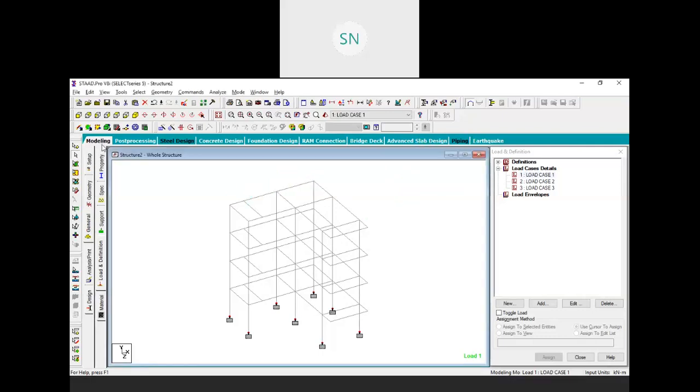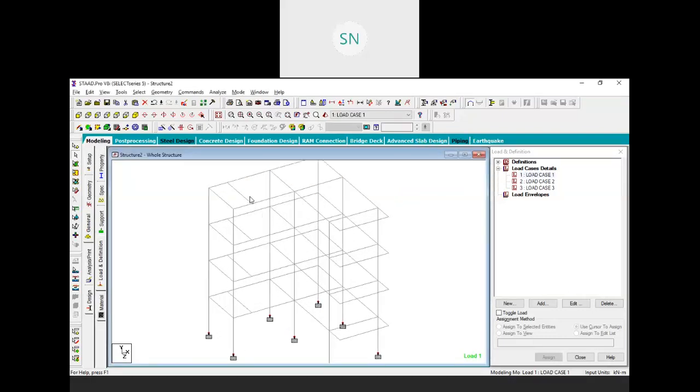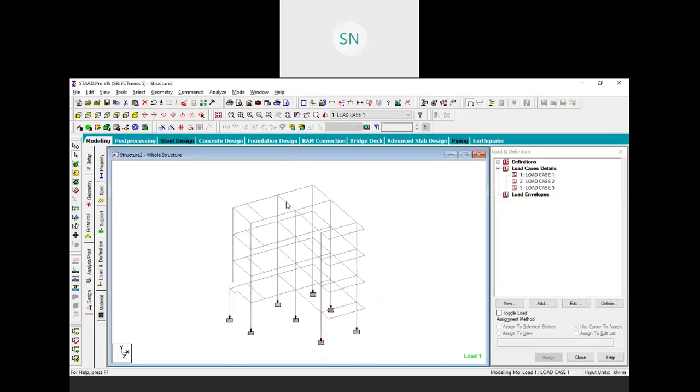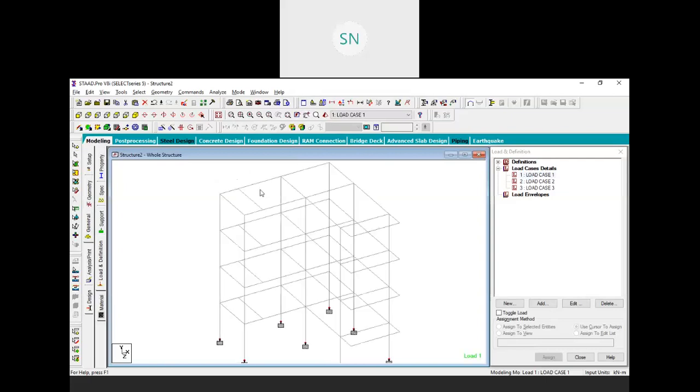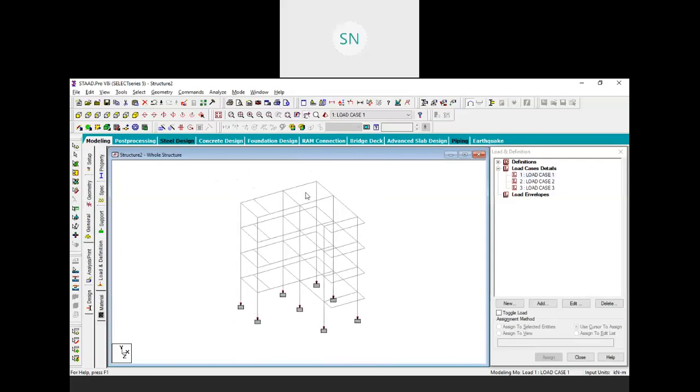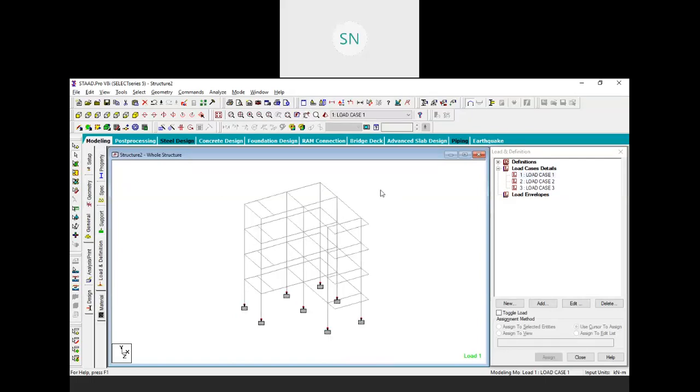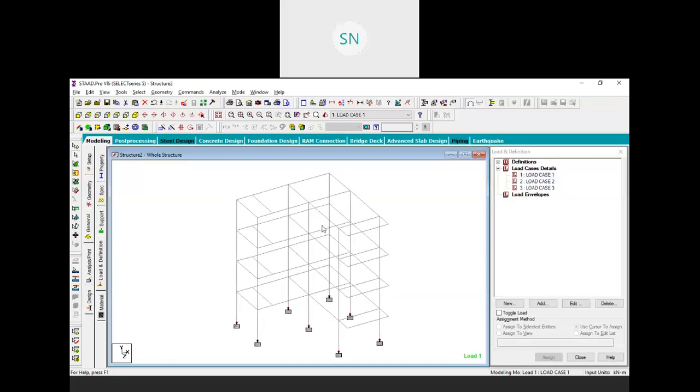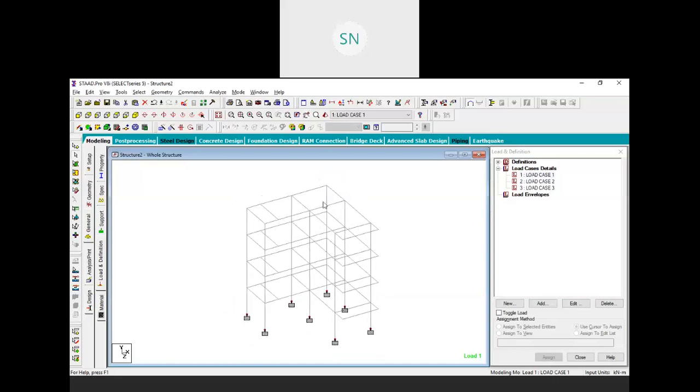Now in our case over here, we apply a cross section property to our structure, right? We create a structure. So now StaadPro has knowledge about volume. So what is the volume of this structure that StaadPro already knows? So we don't need to calculate volume, right? Then the next thing, density. So we apply material property also where our density is there. So StaadPro knows what is the weight of this structure actually, right? Do you agree with me?